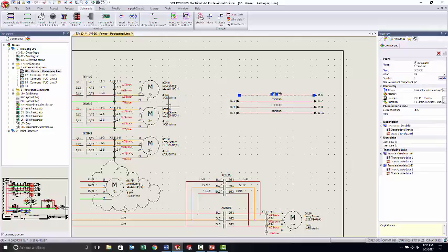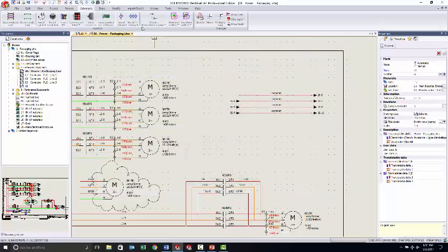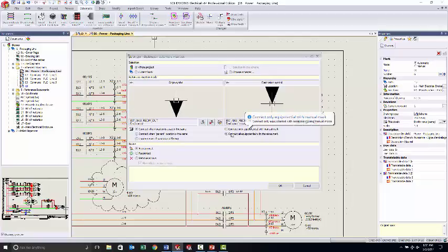So it won't go from one source to multiple children. I think that's got to be one of those other drop downs. So let's look at those other drop downs. Under this automatic insertion, that's probably, let's see here, connect only equipotential with manual mark. Connect if location is different. Connect when parent location is the same. Connect when location is exactly the same. So yeah, it's only going to do it in order. It's not going to merge all those as if it were a distribution block.